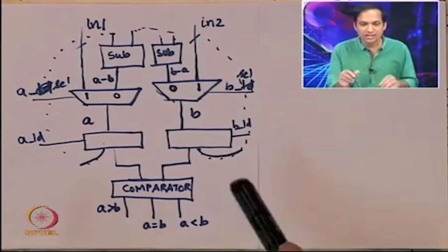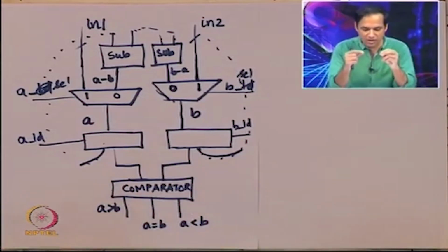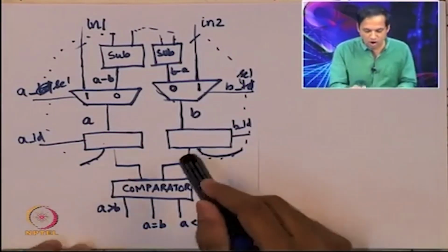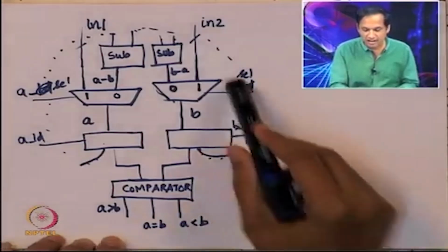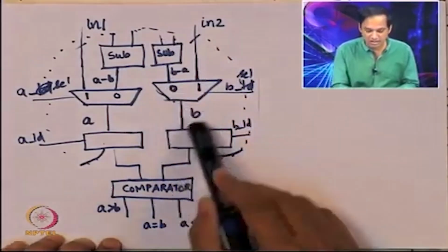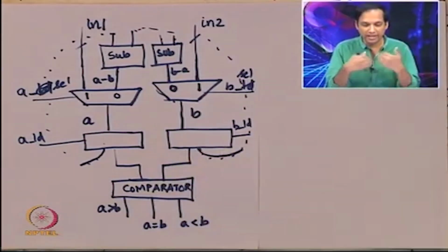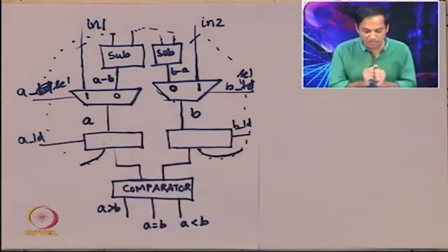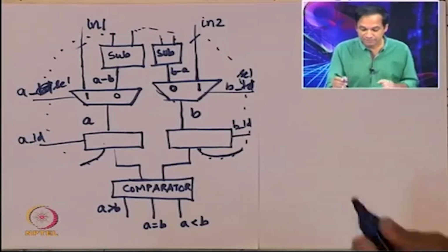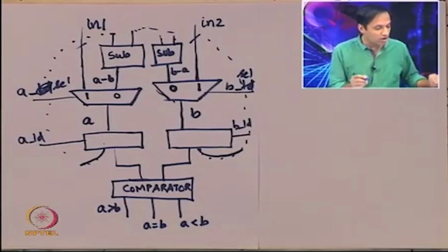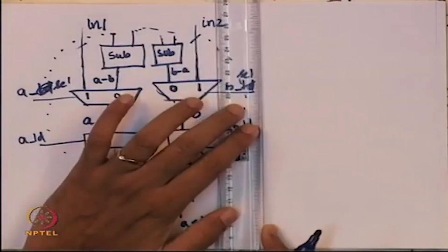So, what we are seeing is the data flowing from, you can think of it as data flowing from the output of this register going through some combinational logic, coming back to the register itself. Under some appropriate conditions, you either change the register or you keep the register as it is. So, this is the notion of what is called a data path. I am going to draw a block diagram kind of a setup for the data path.